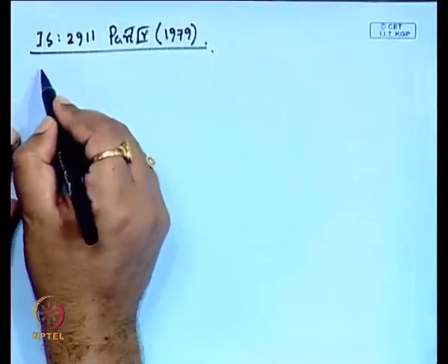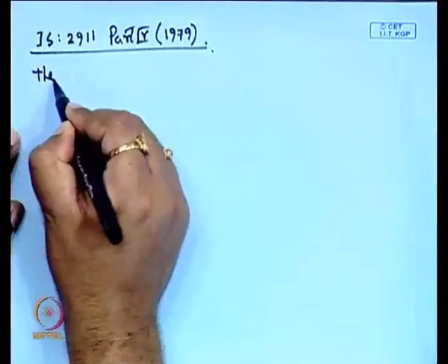So, the pile cap is used, where the load is applied with an increment of 20% of the safe load, and as I mentioned, the safe load is calculated based on the static expressions. The settlement corresponding to each incremental load is recorded, which is measured by using at least 3 dial gauges. Now, the allowable load, how will we get the allowable load of the pile?